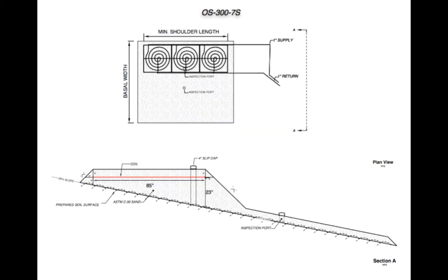And a look at, again, the 300 gallon a day design with the 7-foot coils on a sloping site. You can see we've shifted the coils up to the upper elevation basal area boundary, so we take advantage of all of the potential basal area infiltration as water moves down slope through the soil profile.